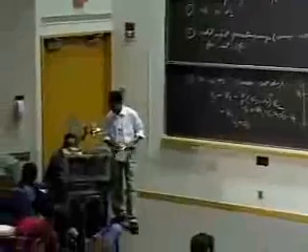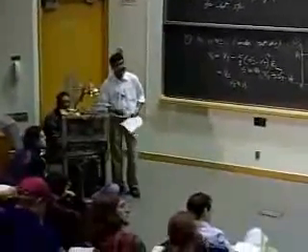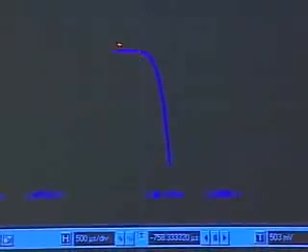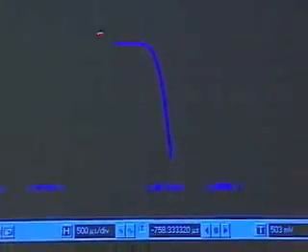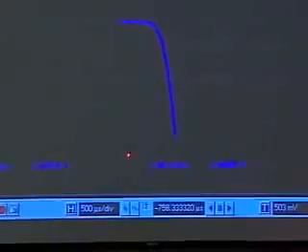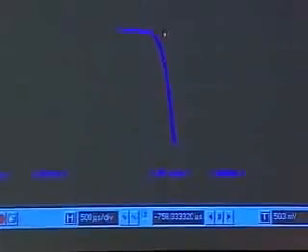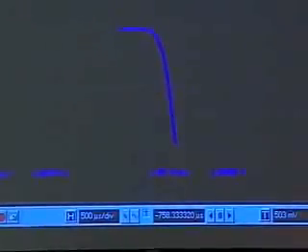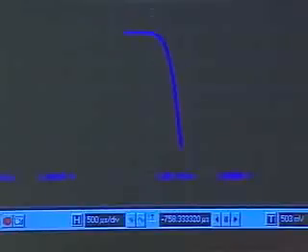Shall we show it up there? So notice that here, that's the same transfer function, and the amplifier output is at Vs until the input reaches the threshold voltage Vt. And once the input goes beyond Vt, the output begins to drop precipitously.